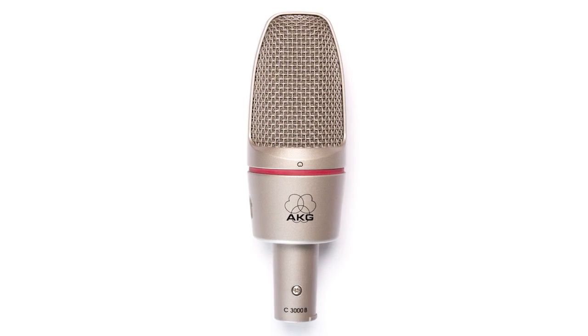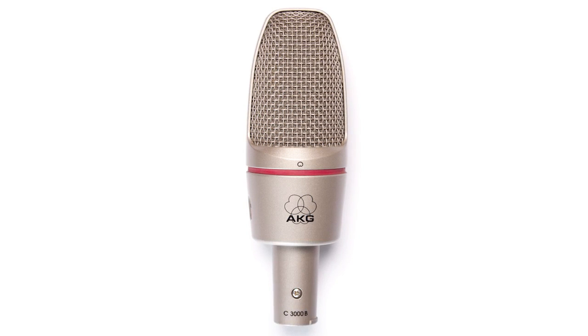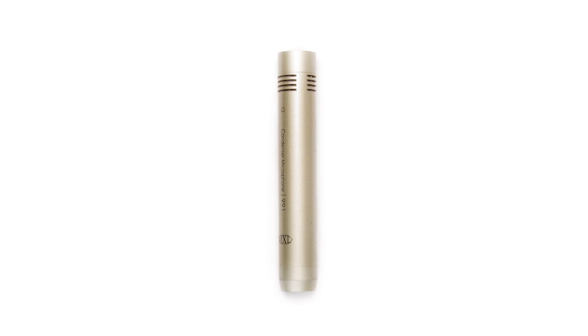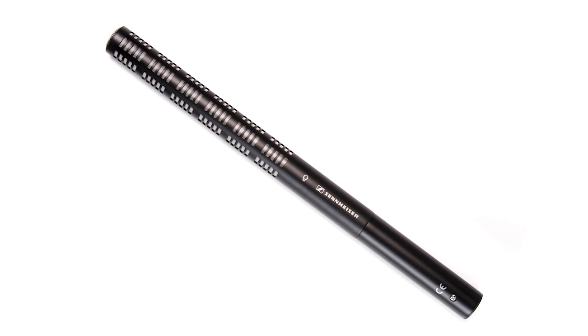Condenser microphones are different than dynamic microphones for a few reasons. The diaphragm element is much lighter than a dynamic microphone, so it can respond very quickly to sounds. Because of this faster reaction time, the sound is said to be more transparent, and condensers are far more accurate than a dynamic microphone. Because of their construction and electronics, condensers are not as resilient to physical shocks and humidity compared to dynamic mics. Condenser mics have excellent sonic characteristics and are widely used in recording and live productions.